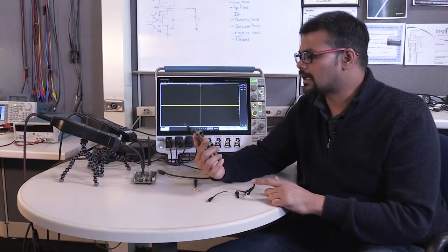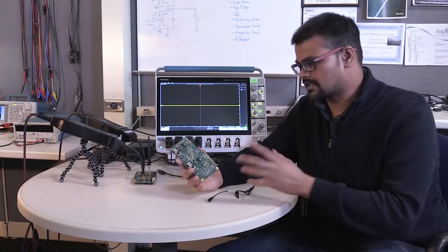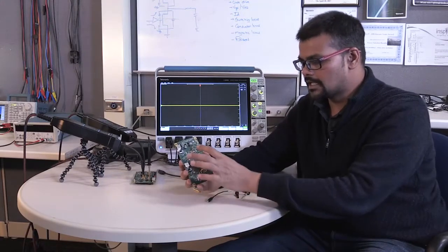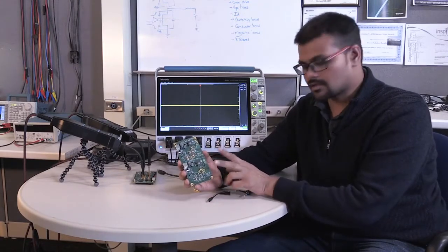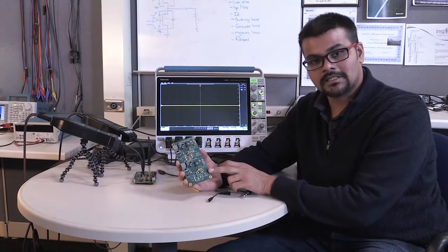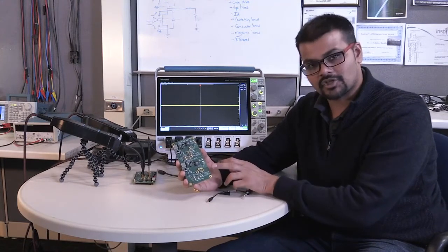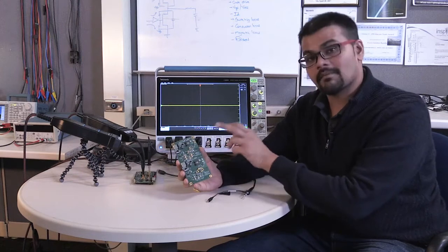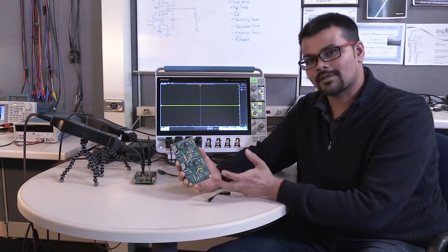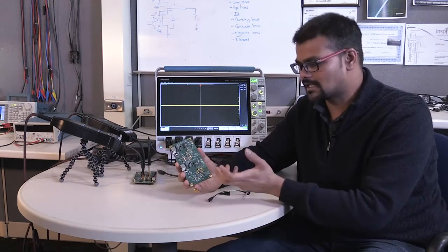So this is a GaN half bridge board. It's based on a GaN product. It's a half bridge, and we have two of those circuits on top and the bottom. They're identical circuits. They're isolated from each other. The one on the top has MMCX connectors on it. The one on the bottom has square pins, so we can compare between those connectors and see the effects of those connectors, right?